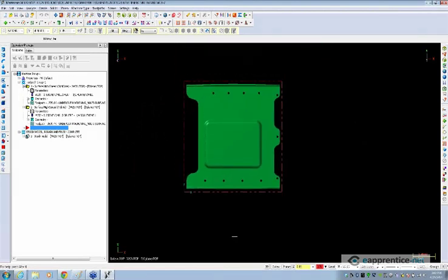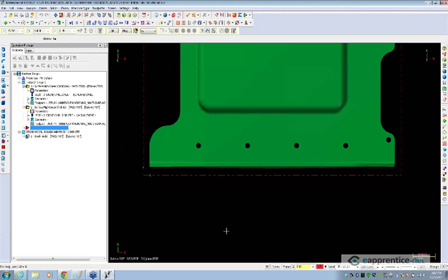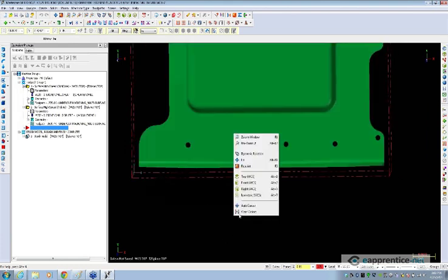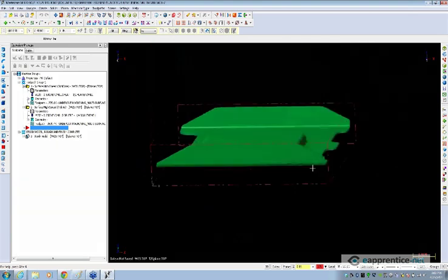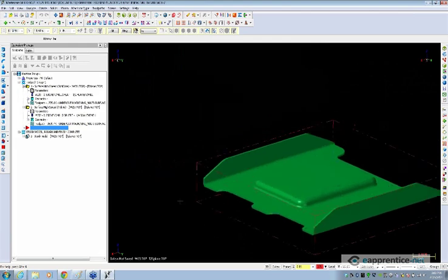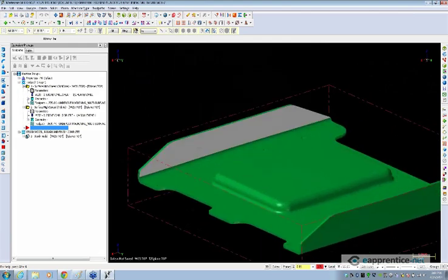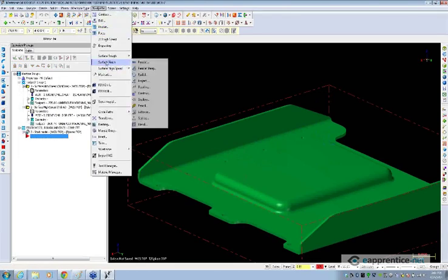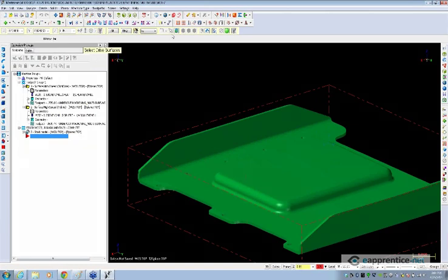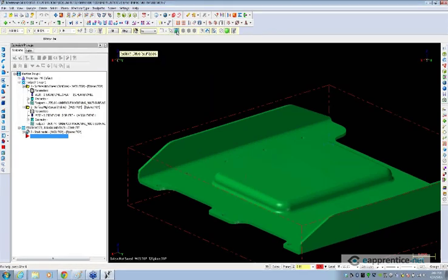I'm going to select top view here. This is my undercut wall that I have to worry about. And I can use either surface finish flowline or surface finish contour. If we use surface finish flowline, that's going to work out pretty well here, hopefully, because it's a single surface. So I can do toolpaths, surface finish, flowline. It says select my drive faces, so I'll choose my solid selection, choose the face option here, and choose this face.